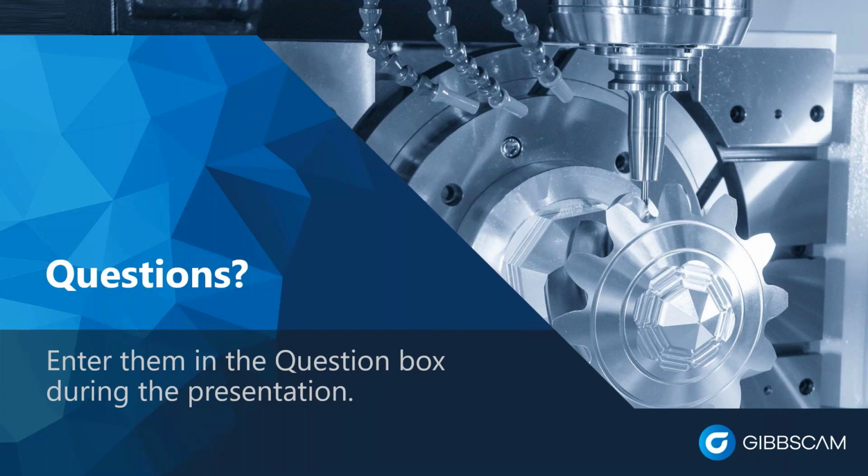In fact, what we're running into more and more is there are customers that only have 3-axis machines or 4-axis machines, but they want to use 5-axis machining strategies. And there's big benefits to this. In a 3-axis environment, you might be able to utilize the side of the tool to do faster machining versus just doing ball end mill point to point over an entire surface.